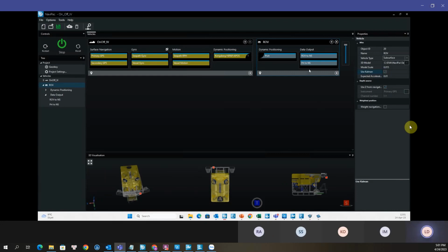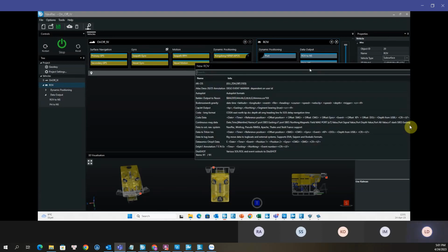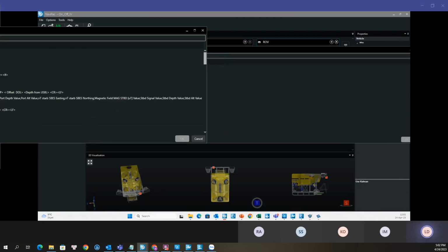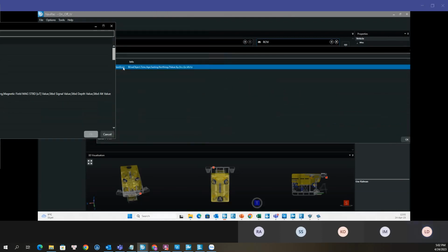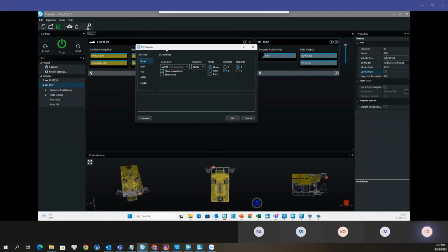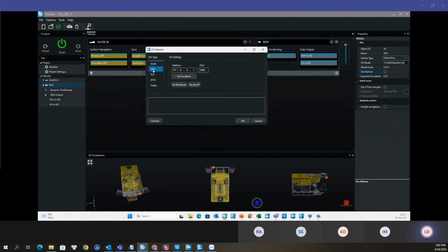Then we can go back and add another data output to the configuration. Right click, add instrument, and then here EXP position, EXP to Naviscan. This one is then once again a UDP IP, but here the port number is 5025, like this.